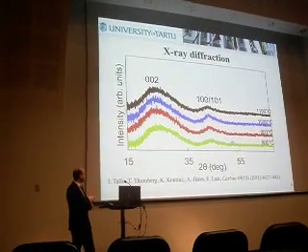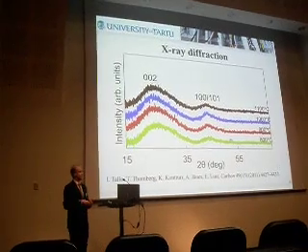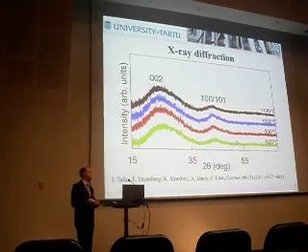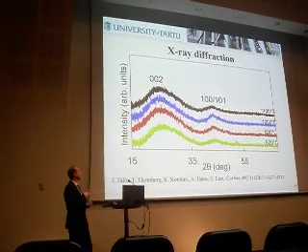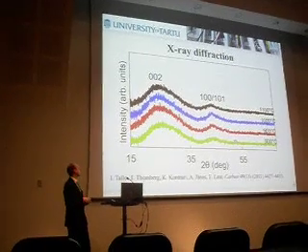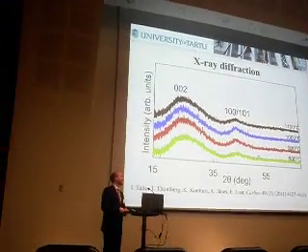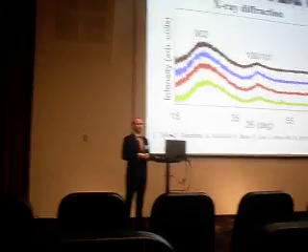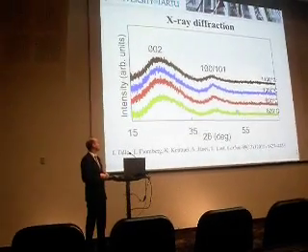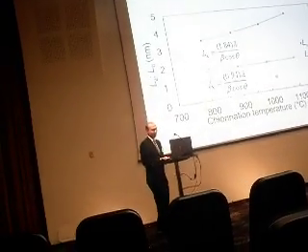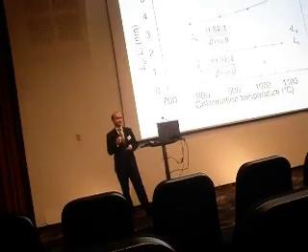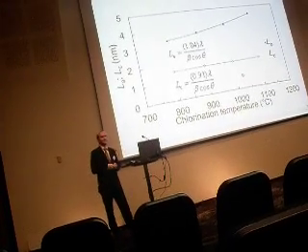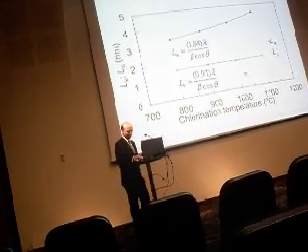There are some peaks in the diffractogram that correspond to graphitic material, but they are so very wide and so, let's say, not high that we can calculate that the material itself is very amorphous, and the crystallite sizes are very small, about 2 nanometers one way and maybe up to 5 nanometers the other way.